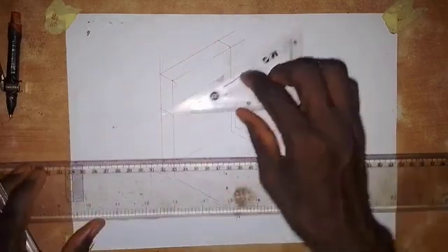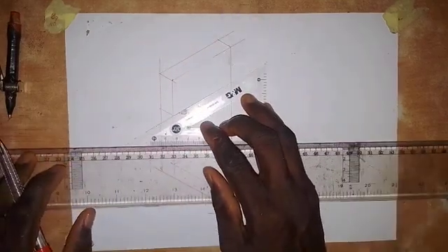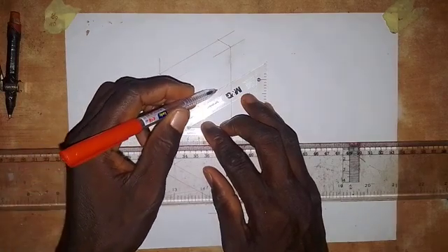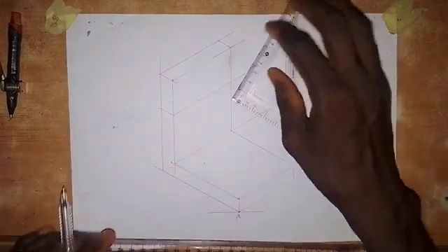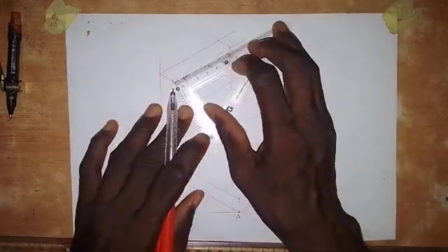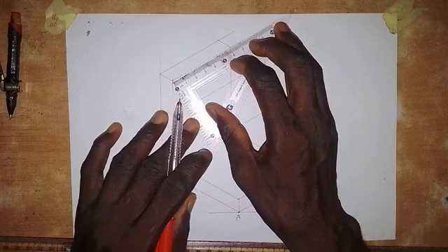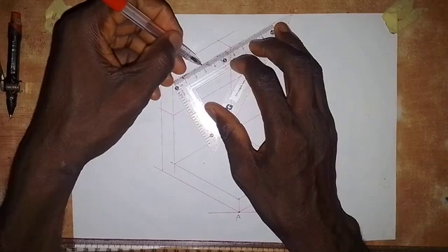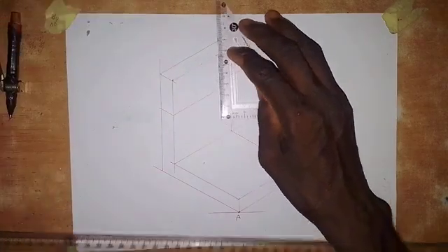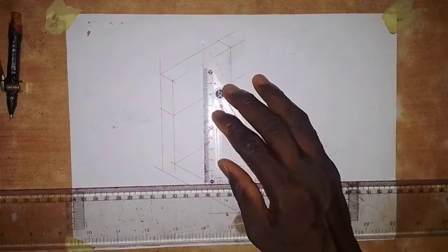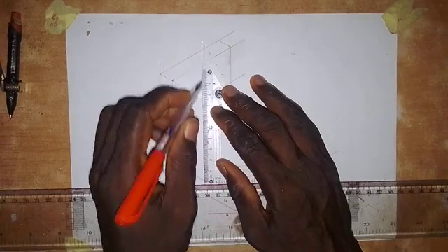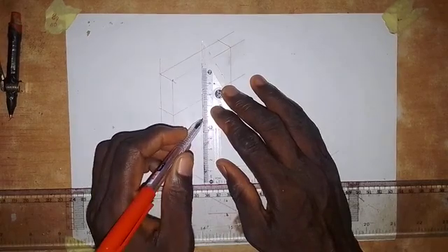And then you turn your set square like this, and then draw this as a center line. Just draw like this, okay. Then this 60, so this is 60 millimeters. This 60 millimeters, we break it down into two to draw a vertical center line. That's 30. So draw a vertical center line here. So from this point, take down a vertical center line like this, okay.